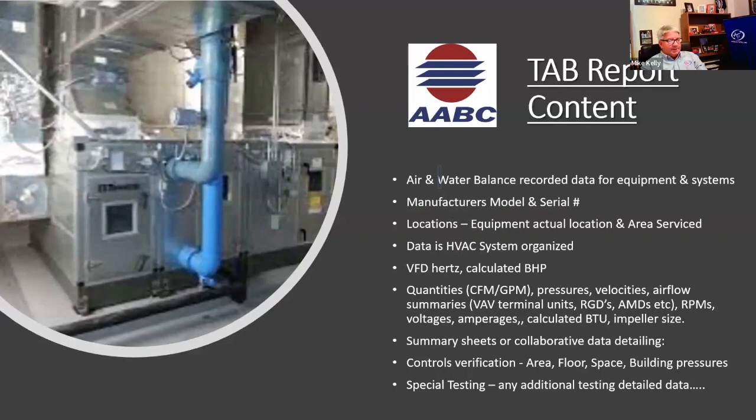Whether it's a pumping system, hot water, chilled water, you just don't want all your flow meters listed, and then you have to search: well, these are all the chilled water flow meters. Where's the pump that says we got 1200 GPM? The pump says we got 1500. Well, if that was listed by system, there should be a note in there explaining how you got 1500 out of the pump, but only 1200 out of your flow meters.